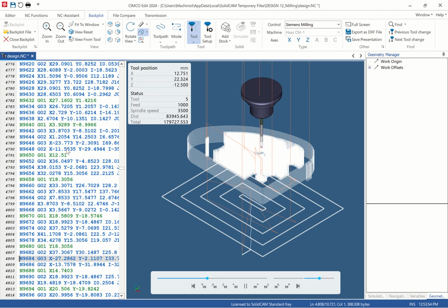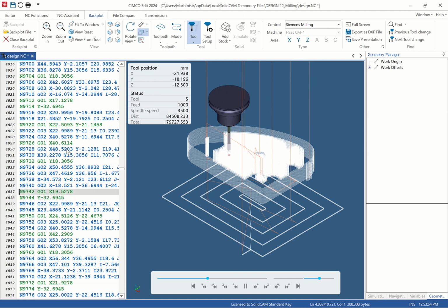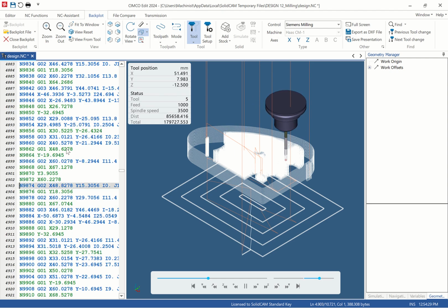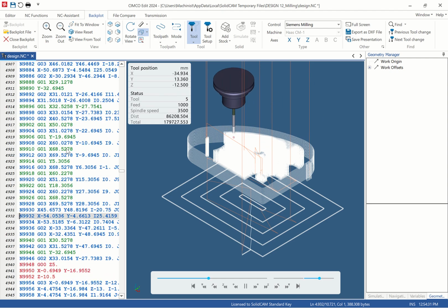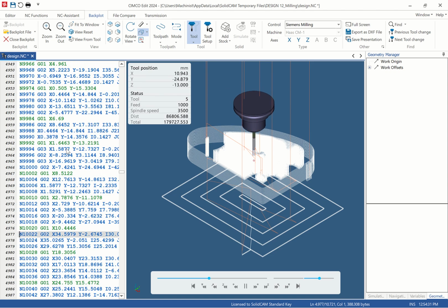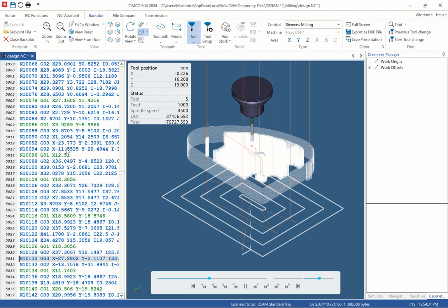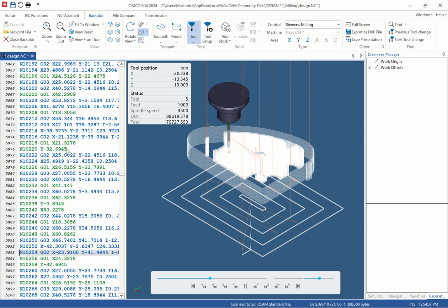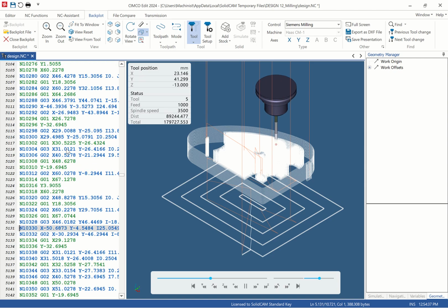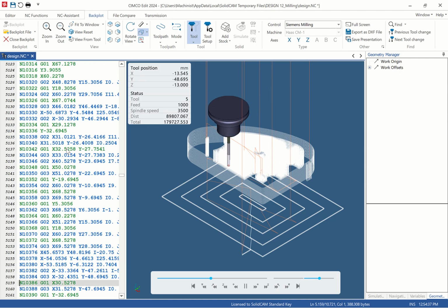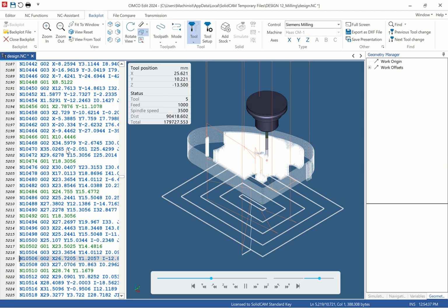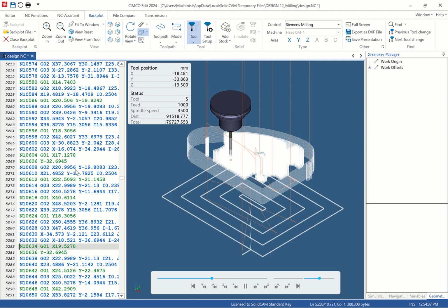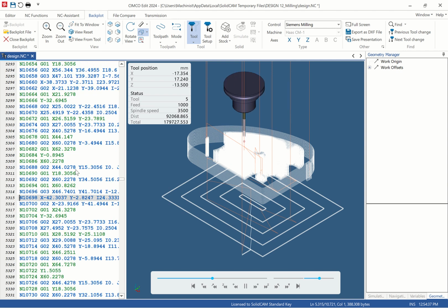For CNC, there are different controllers. We have Siemens controller, Fanuc controller, GSK, HNC, Fagor, Mitsubishi. There are so many of them that you can use. So the CNC may be either for solid machining, or for laser, that is sheet metal, or for router, for woodwork, or 3D printing, or plasma cutting, or rubber cutting. It depends on which kind of CNC, but the codes are the same. When you're programming, the codes are the same, but the method of programming may be different.